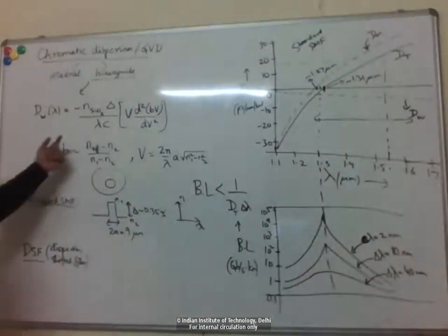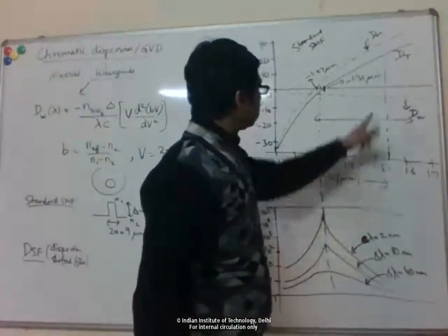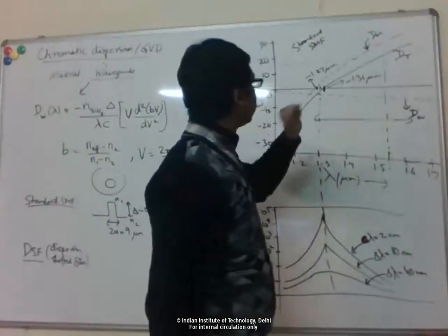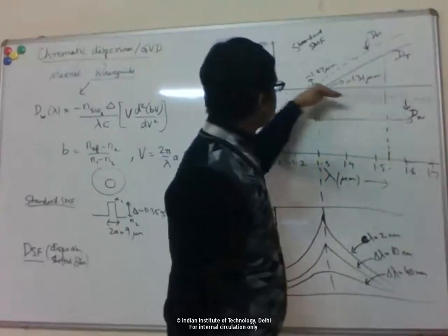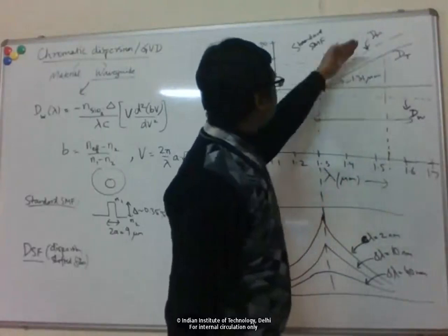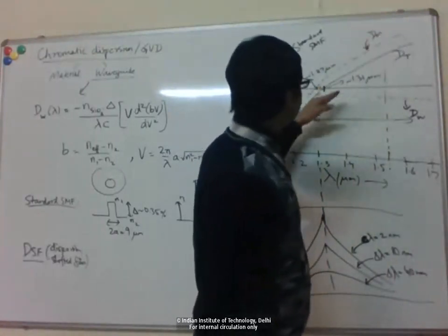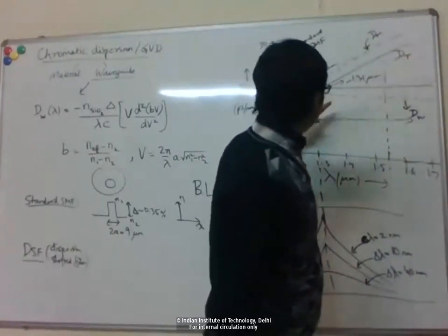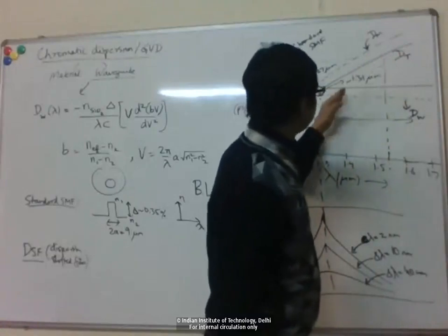Let's say I want to shift this zero dispersion point to higher wavelengths, so I want to use higher wavelengths but lower the dispersion there. One way to do that is if this waveguide dispersion was more negative. That will shift this material dispersion more down, so the total dispersion will shift downwards and to the right, and the zero crossing will move towards the right.